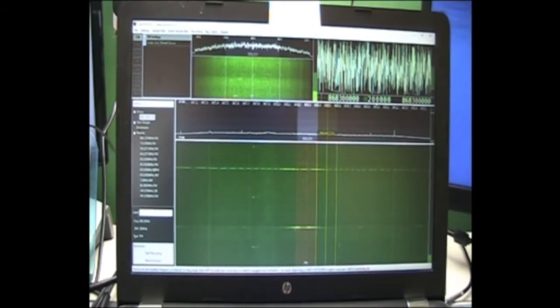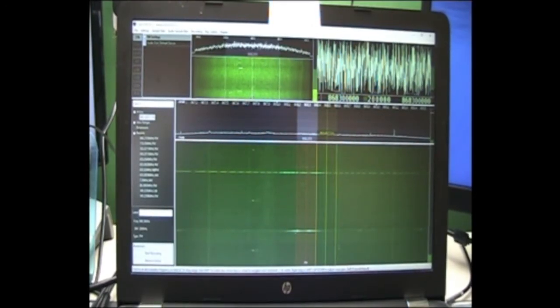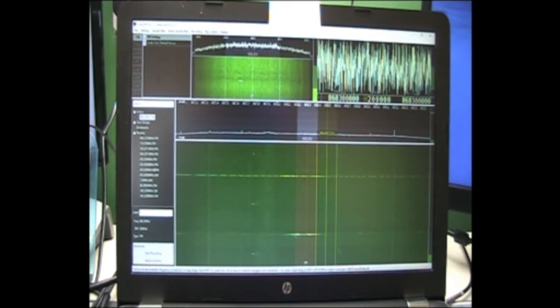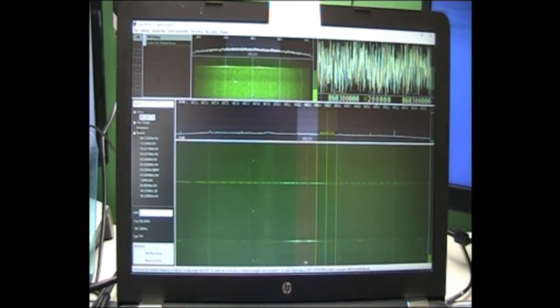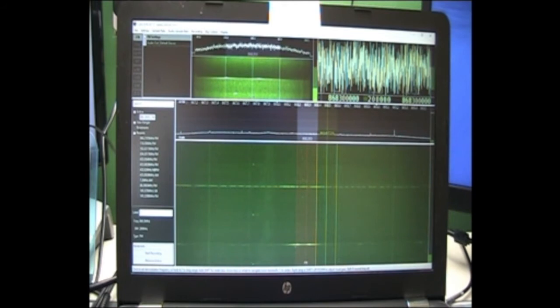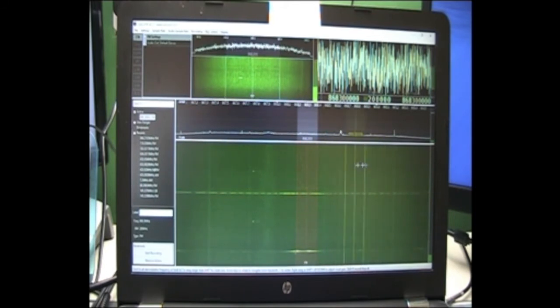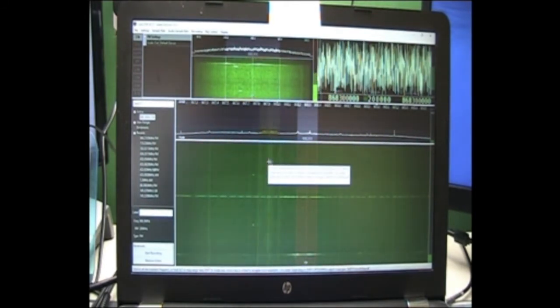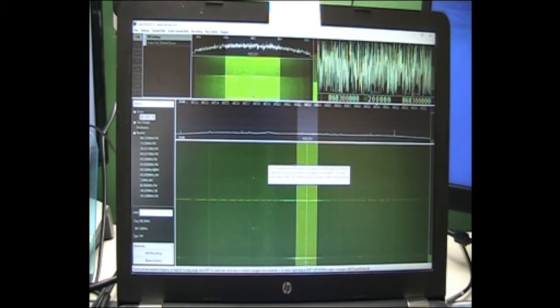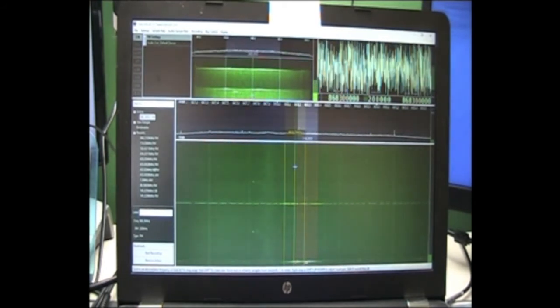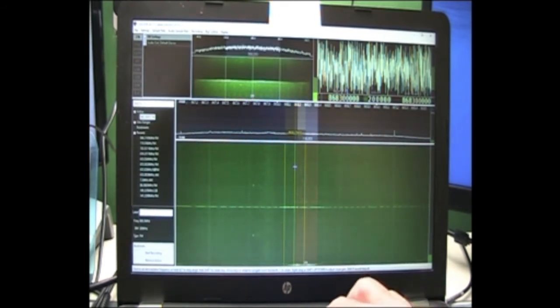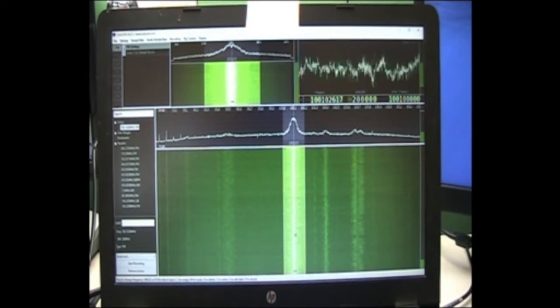Using this software, I'm able to investigate the radio spectrum to see what signals are around. Now at the moment, the radio is tuned to the 868.3 megahertz of the weather stations, and you can see every so often a burst of data comes over, and that burst of data is carrying all the numerical data for the current weather situation onto that base station. You can't really tell from this display. This simply shows you what the radio frequency and atmosphere is looking like.